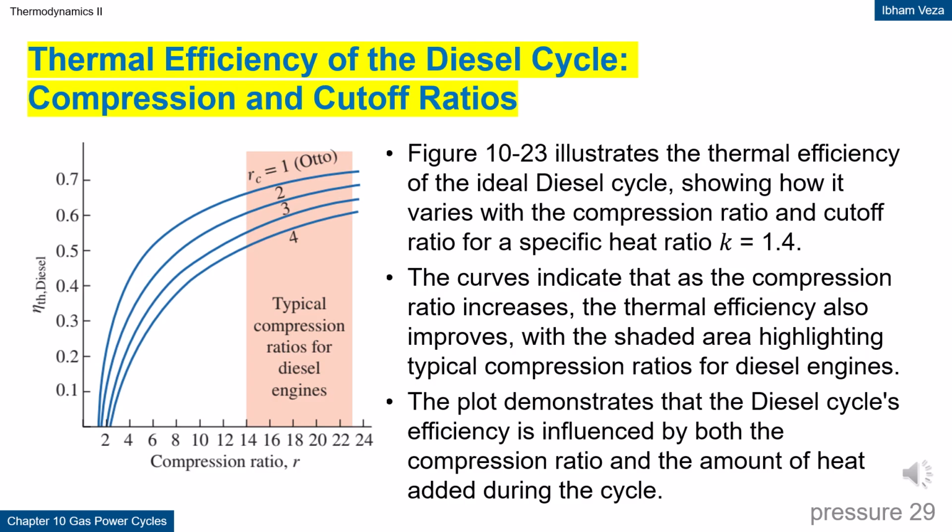Thermal efficiency of the diesel cycle. Compression and cutoff ratios. This graph shows how the efficiency of the diesel cycle is influenced by the compression ratio and the cutoff ratio. For a given K value, increasing the compression ratio generally increases efficiency.